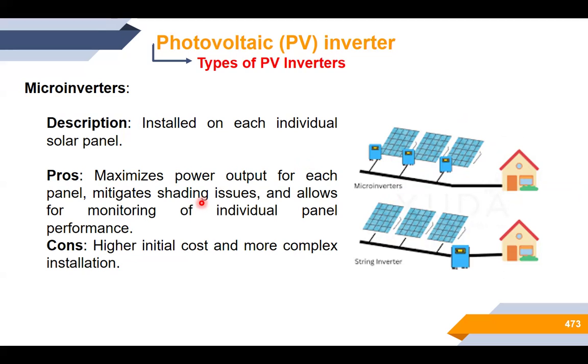The first and most important advantage of this situation is the mitigation of shading issues, because each module is connected to its own inverter. Of course, we will have higher initial costs and a more complex installation at the beginning of the PV installation.